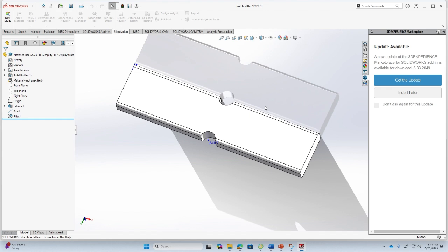So essentially, as part of this, I will show you some ways of, for example, simplifying the model, but then later I will also show you the effect of what we call mesh convergence, okay. So what do I mean by that? Essentially, one of the fundamental reasons that you were not able to get the stresses correctly was because you were considering the stresses to be uniform in certain regions, right? The finite element analysis also has to make certain assumptions, okay.